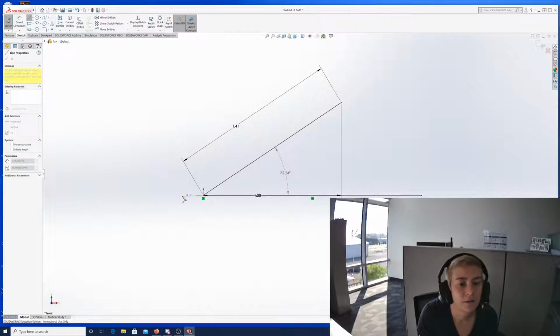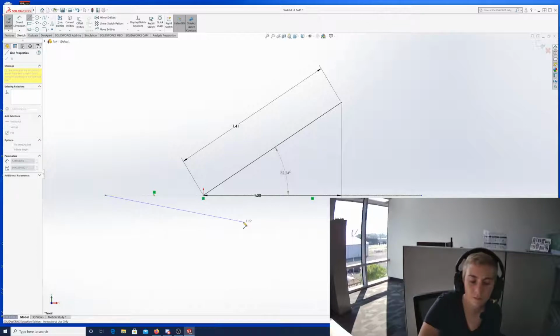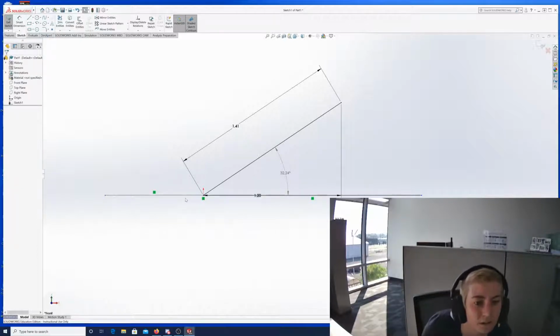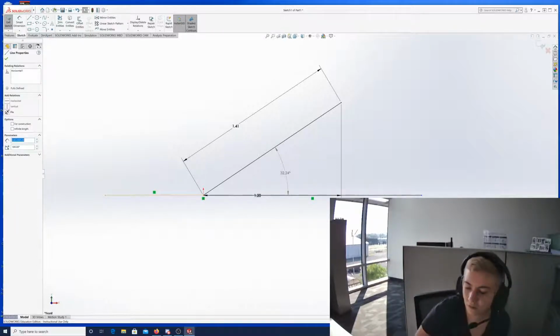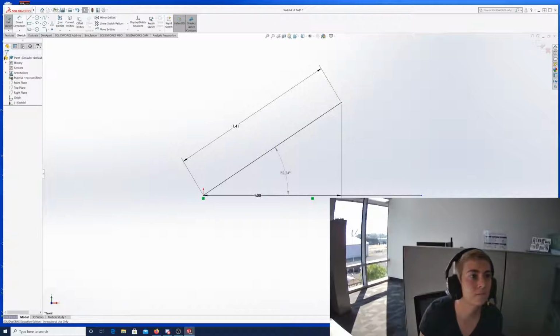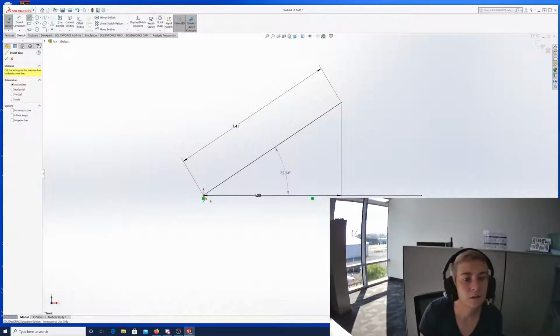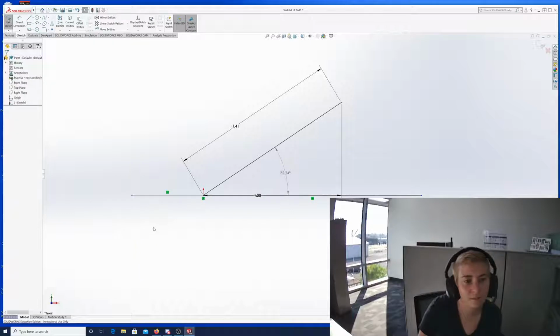No, but that's a relation. So like this, I'll make a horizontal line right here. See how it kind of snaps to a horizontal. I think that was like a dotted line or something that I drew there, but let's try again. So another type of relation, like that's a horizontal line. I'm not sure why it's showing up really skinny like that.